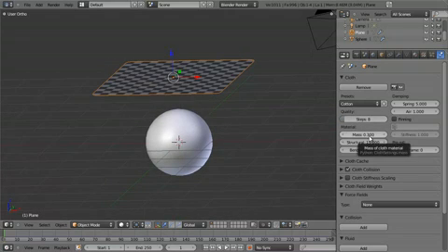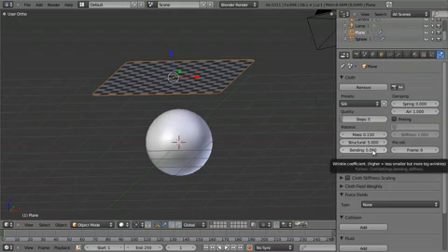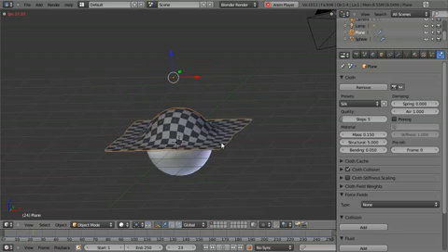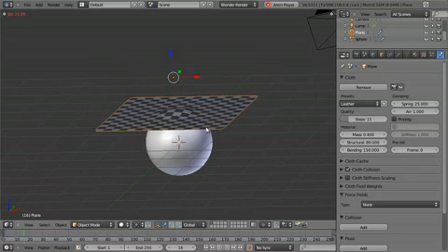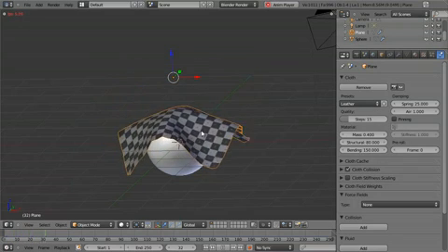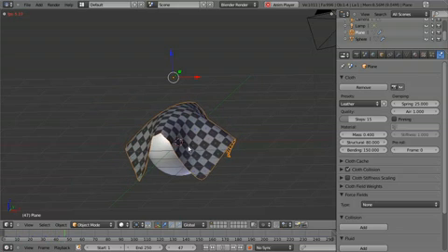Then we've got things like the mass, so the mass of the cloth material, the actual weight of it, the structural stiffness, so how well it holds its shape. You'll notice things like leather have a much higher structural stiffness than, say, things like silk, which has a very low structural stiffness. Then we've got our bending, so the higher the bending, the more big wrinkles there are, but less smaller. So if we turn this down, we see a lot of smaller wrinkles, but not very many big wrinkles. So on things like silk, we got a very low value here. On leather, we have a much, much higher value here. So really, we don't see any little surface wrinkles. We just see these big kind of form wrinkles.